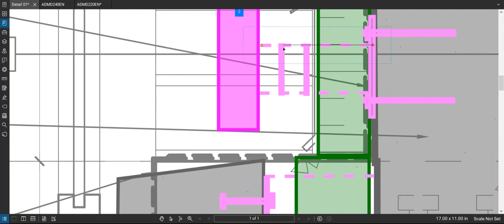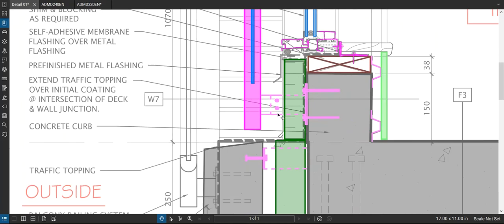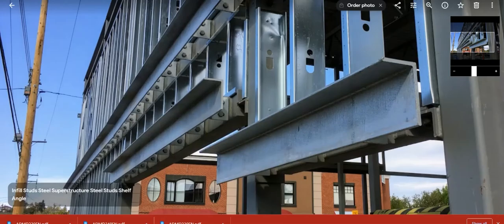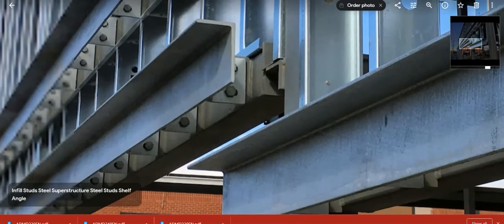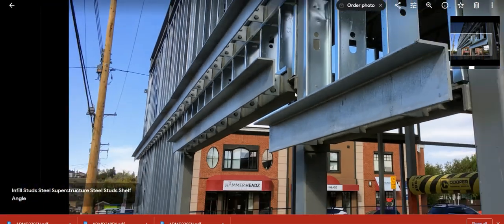So let's say there's a knife plate coming out to here, okay, and then have another plate come off the posts and then actually bolt to the other knife plate, and that'll just allow someone to take the railing off one day and replace it. And again, the idea I'm getting at there is something like this situation here, where there's two plates overlapping and then some bolts put through it.